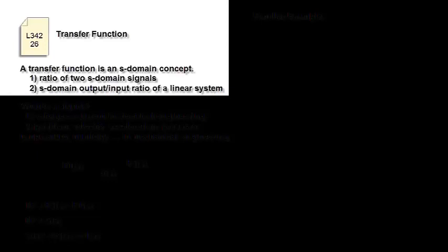What is a transfer function? A transfer function is an S-domain concept. It's really two things. It's a ratio of two S-domain signals, and at the same time, it's an S-domain output-input ratio of a linear system.